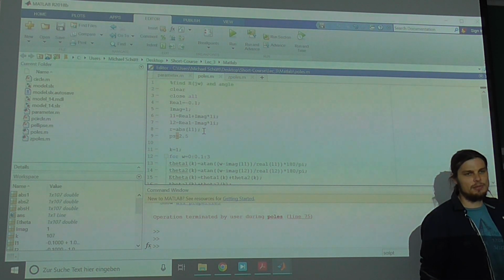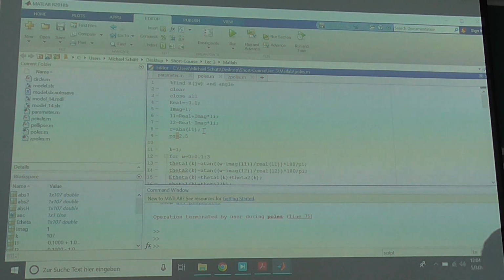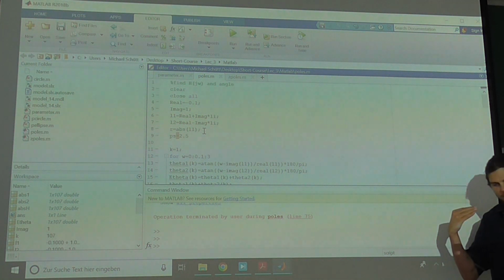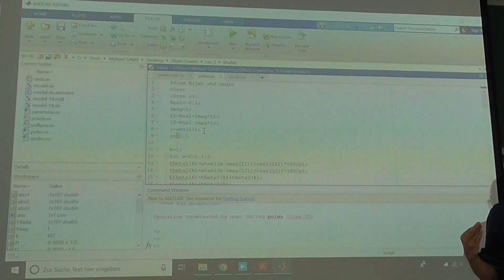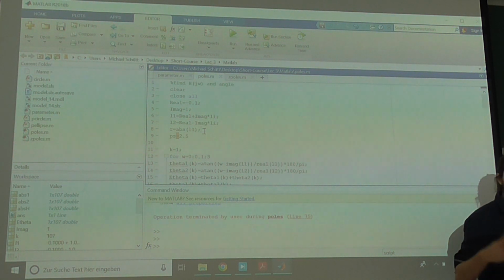Robustness is still an issue, absolutely. But robustness we take care of with what? With our state feedback controller, and it basically looks like determinants anyway, right? Yes. So really this dynamic stiffness is what you should be looking at if you design your state feedback control. You shape dynamic stiffness for disturbances, for robustness, for all of these things, and command tracking we try to get with your feed forward.